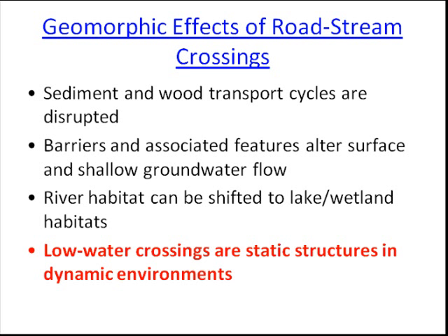Since, again, these road crossings are meant to be static in a changing environment, it's a really tough standard to meet. And in many settings, especially where sediment and large woody debris loads are high, maintaining low water crossings can be difficult over time. However, looking at a few watershed factors during the planning and design phase can improve structural longevity and decrease the amount of maintenance necessary over time.